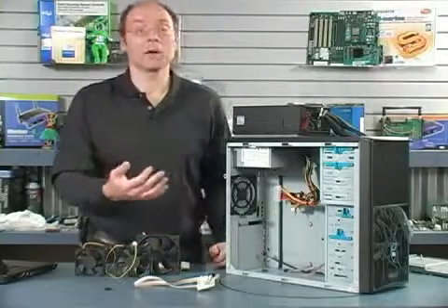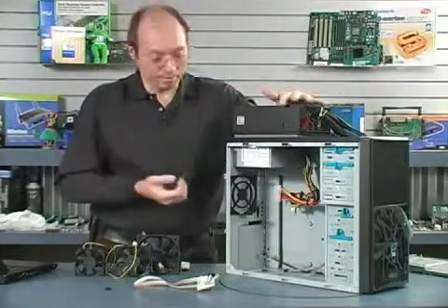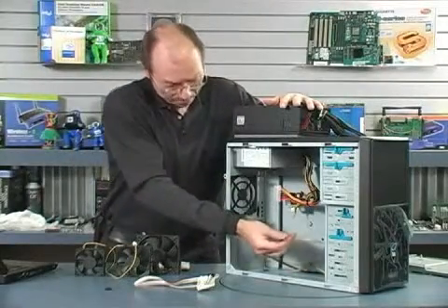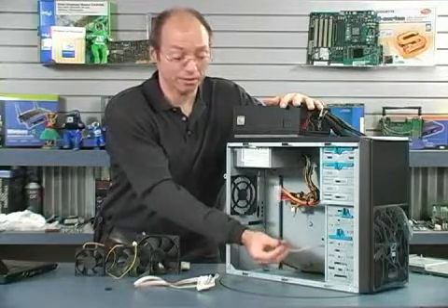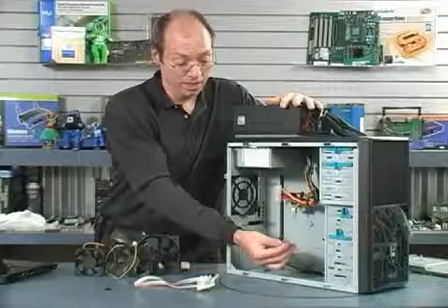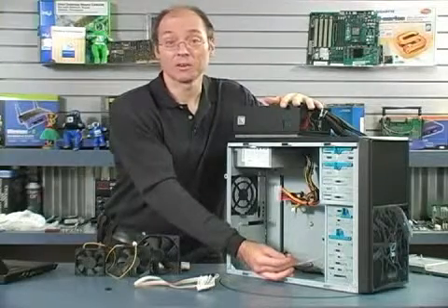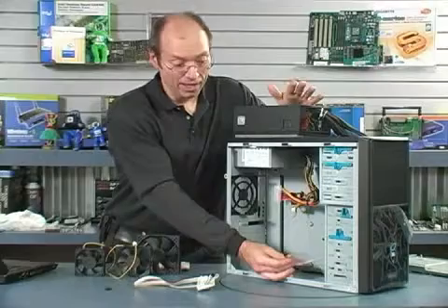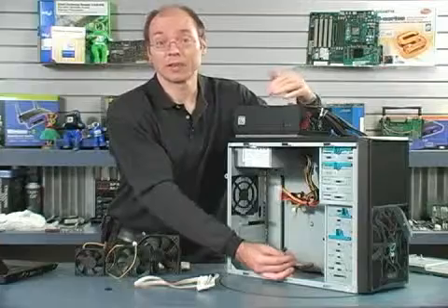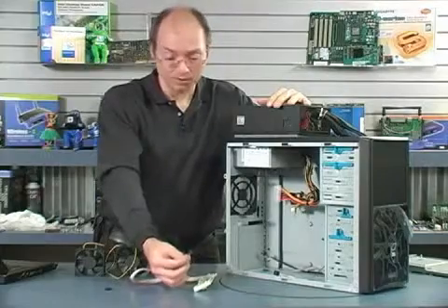Now, if you've ever seen cases from companies like Dell, Gateway, or, in other words, pre-built, mass market PCs, you'll note that they almost always have cases with front panel connections that have a single connector. This is a one keyed connector that makes all of those connections at the same time. Now, believe it or not, Intel created a standard for this front panel connector more than 10 years ago. In fact, I think it's like 15 years ago now. And almost any motherboard that I would ever buy follows this standard and has this standard type of connector. So the need for these individual pins is ridiculous.